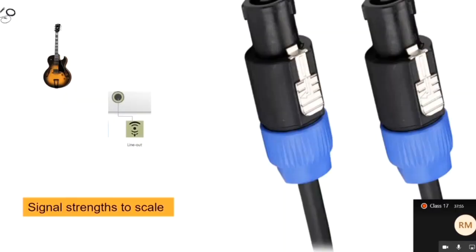I tried to do a scale with this picture here, signals to scale. Notice up here in the top left-hand corner, we have a microphone and a little microphone cable, tiny little signal, and then a little bit bigger, the instrument level, like this electric guitar, and then slightly larger and medium-sized, robust signal is this line level. You might see this as a line out on your computer, or on some audio device, maybe a digital keyboard.